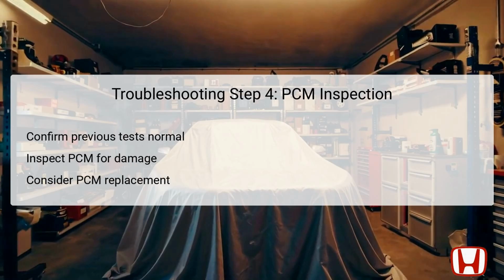If all prior tests have confirmed normal conditions for the APP sensor and its associated circuitry, the next logical step is to inspect the powertrain control module, PCM, itself. The PCM is responsible for interpreting the signals from various sensors and is central to vehicle operation.